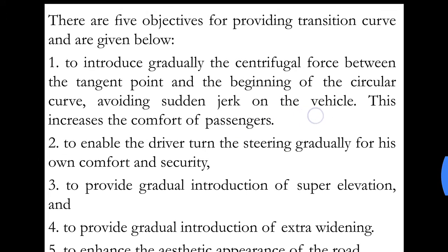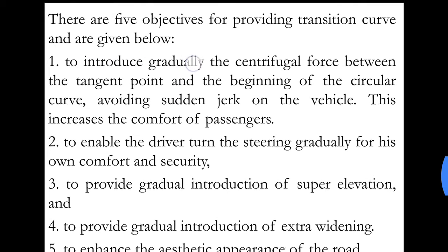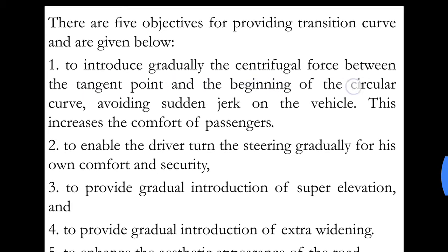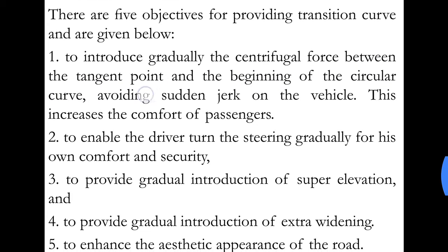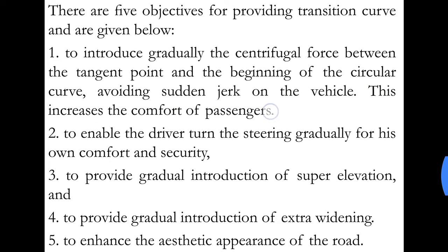Now let us see what are the objectives of providing transition curves, or why do we need transition curves. First point, to introduce gradually the centrifugal force between the tangent point and the beginning of the circular curve, avoiding sudden jerk on the vehicle. This increases the comfort of passengers.